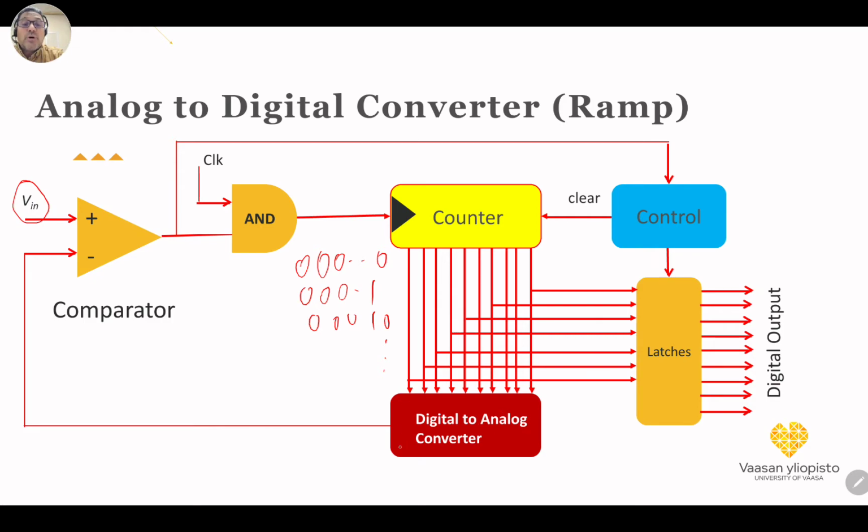It is quite easy to implement the digital to analog converter. So the output here, assume that it is zero. For example, we assume that the minimum of this signal is zero, and once the input signal is greater than zero, what happened? Here we will have positive, like plus one, for example. Once we have plus one here, it means that this AND gate will be opened, and accordingly the output here will be one or zero based on the clock.